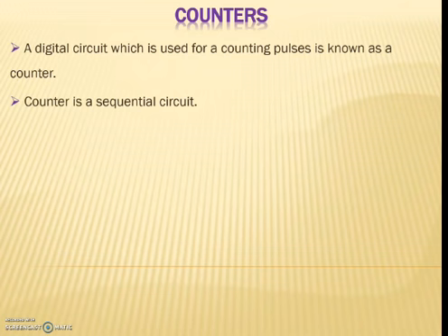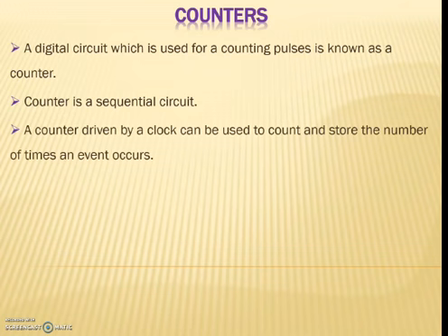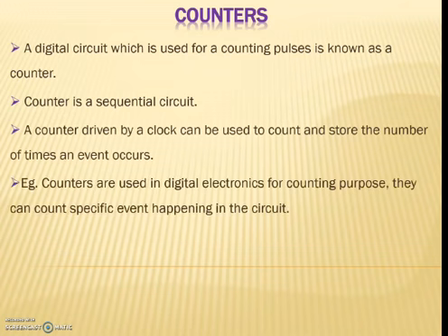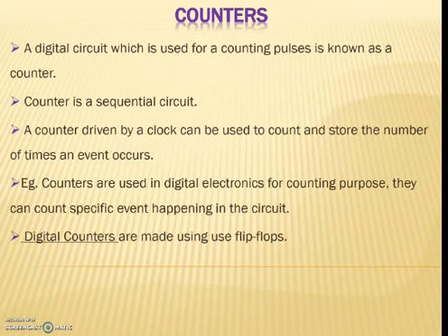A counter is a sequential circuit. Hope you all remember what a sequential circuit is, right? Yes, circuits whose output depends not only on the present combination of inputs but also on the past outputs are called sequential circuits. A counter is driven by a clock and can be used to count and store the number of times an event occurs.